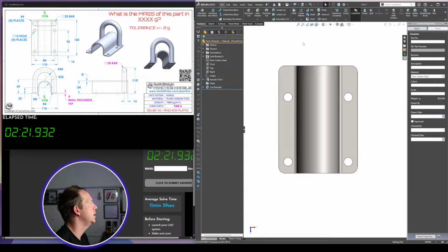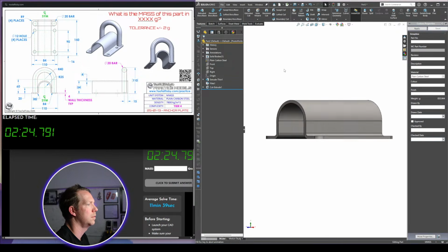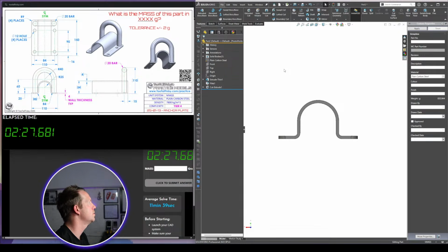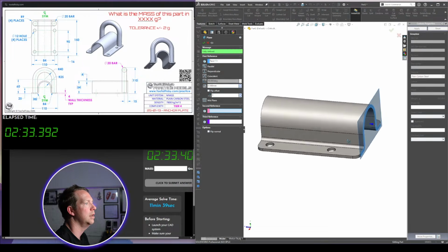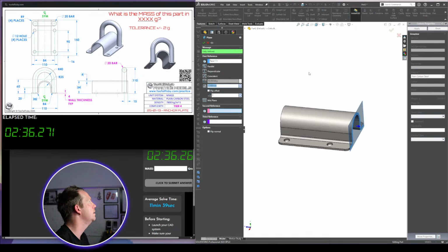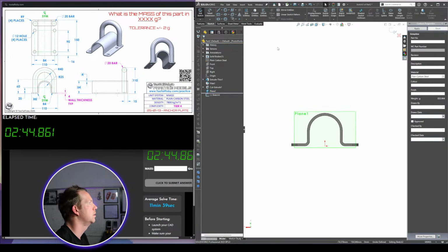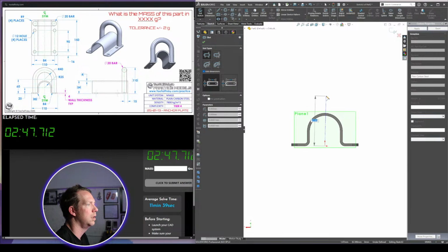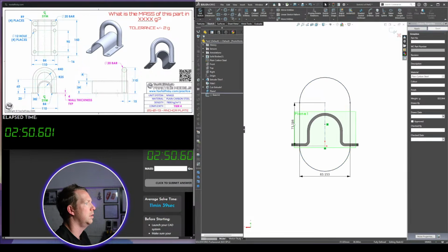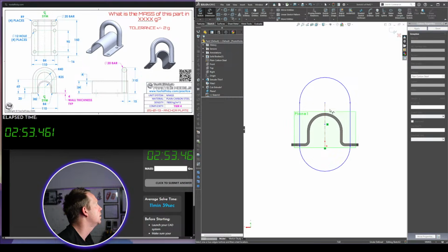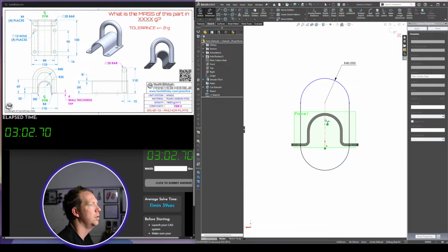Okay, then we just need to do the loft at the end. You could either exploit this, we won't. What I'll do is put a plane here, offset that plane by 15 on that plane. Then I'm going to do a sketch, which is a slot. And the distance of that is radius of 40. What is the height? Total height is 60 from the origin.